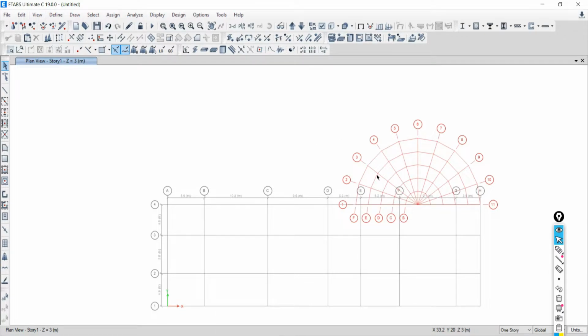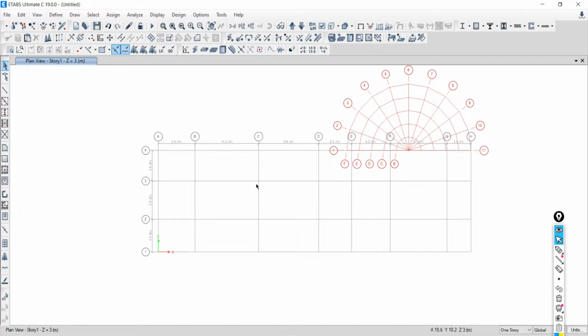This is about the grid system preparation by the ETABS quick template option. Here we are going to prepare the grids in the software itself. Why is this recommended by experts? Because when you find a point, you get the exact intersection of these two lines. If I prepare anything from this point to this point, exact line modeling will be there.